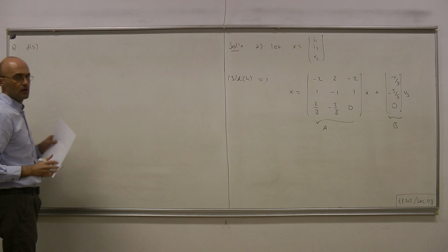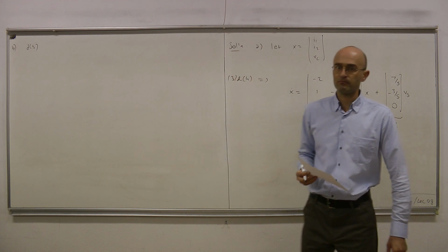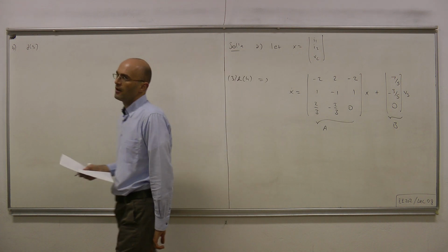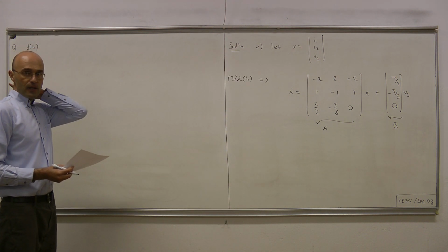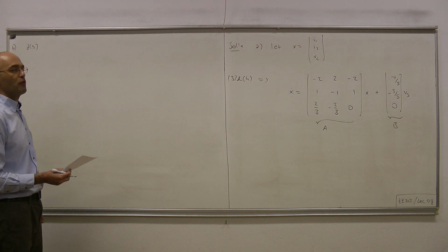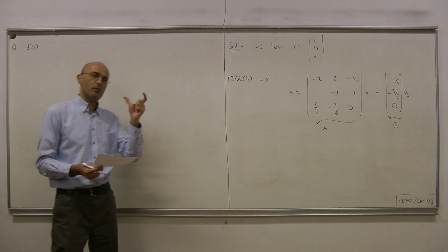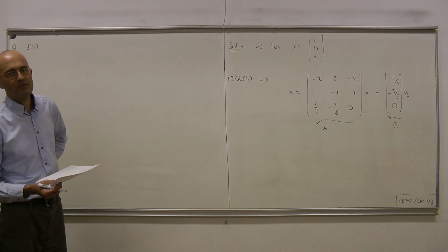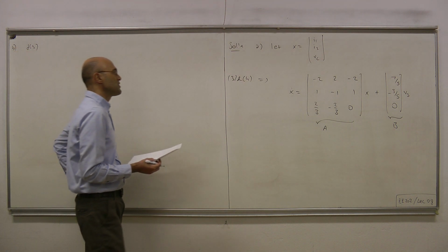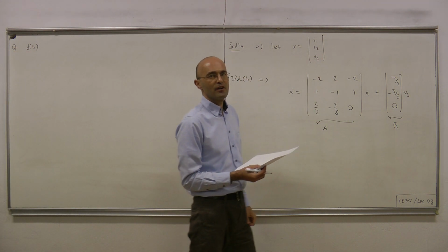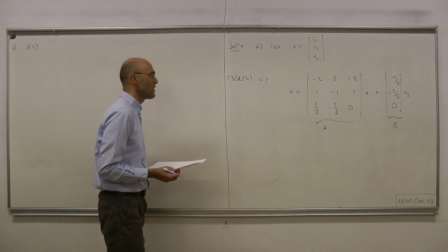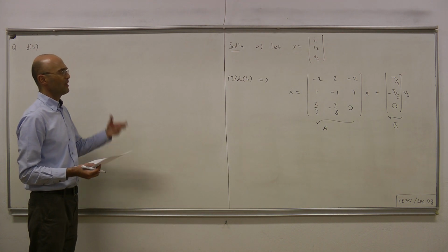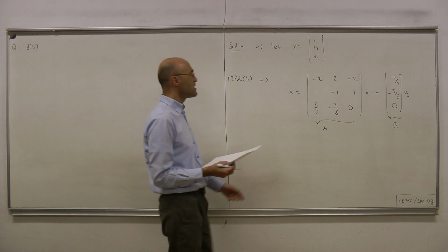Now, remember from the first and second order circuit analysis that we have performed in circuits, what we called the natural frequencies were the roots of the characteristic polynomial. And the characteristic polynomial we directly extract from the scalar differential equation. Now, in this case, we don't have a scalar differential equation, we have a vector differential equation. And therefore, the characteristic polynomial doesn't appear